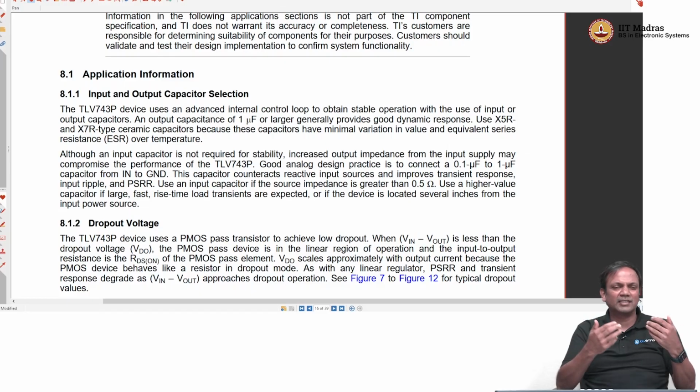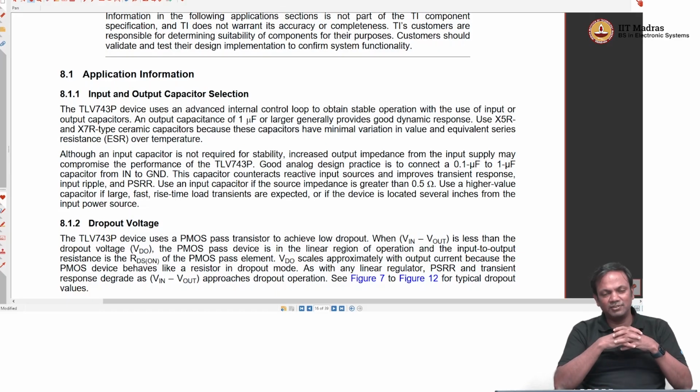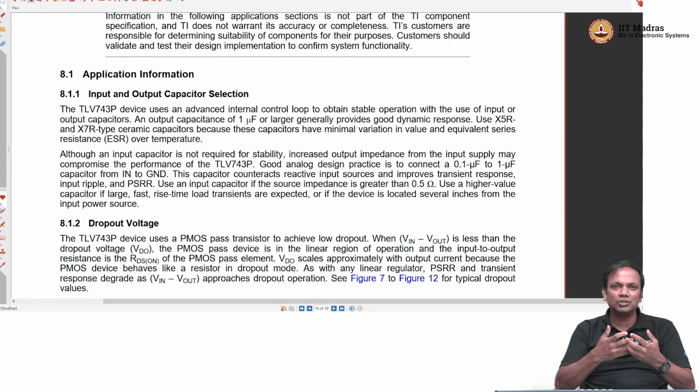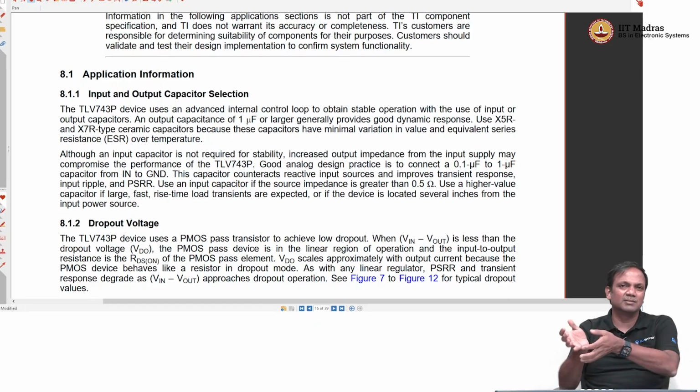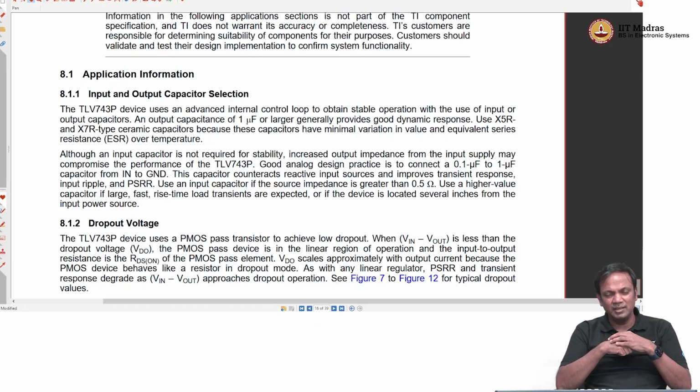Depending on the type of compensation you have done and the type of circuit you have, what might happen is that you have a first dominant pole where the gain starts dropping, and then you need to make sure that the gain drops below 1 or 0 dB. 1 in the number system is the same as 0 dB. The gain must drop below 1 before the phase accumulates more than 180 degrees. You anyway have negative feedback.